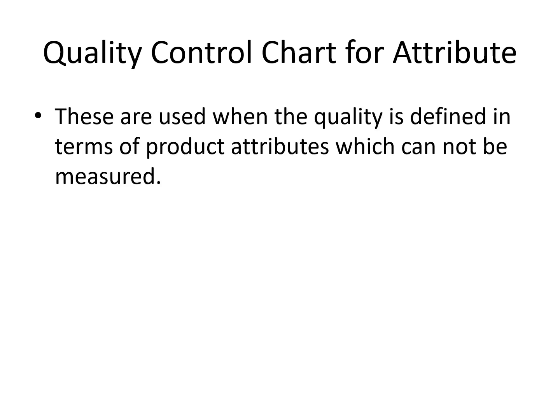Now, coming to the quality control chart for attributes. The quality control chart for attributes is drawn for those quality parameters which cannot be measured, or which just give us whether the quality of a product is good or bad. That's why we call it an attribute. It cannot be measured; there's no dimension to it. The attribute would determine whether the quality of a product is good or bad, whether it is acceptable or not acceptable.